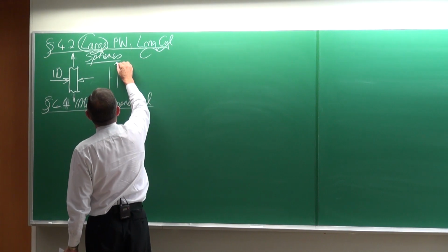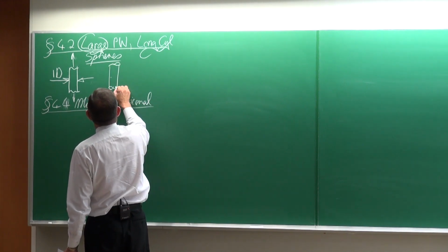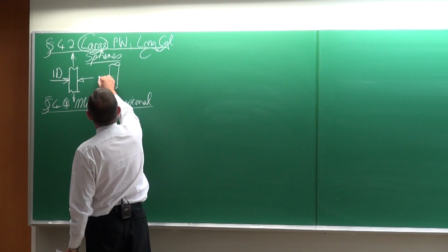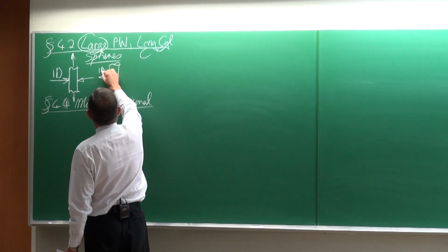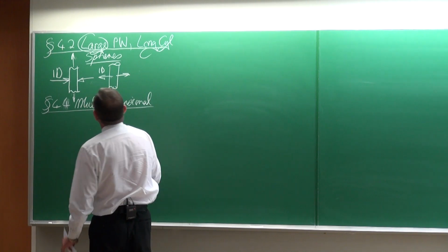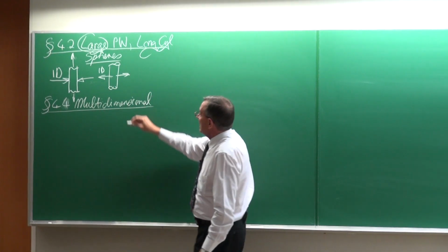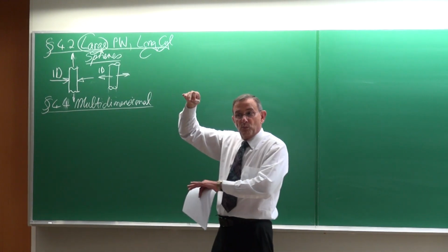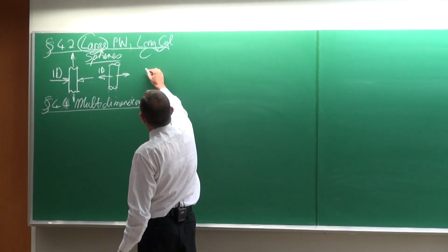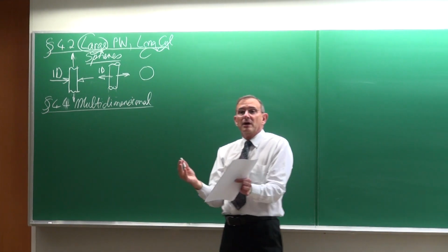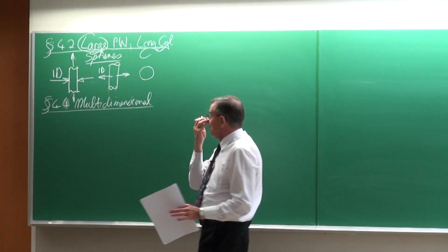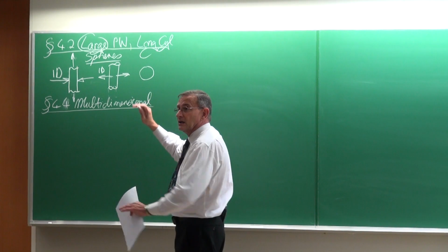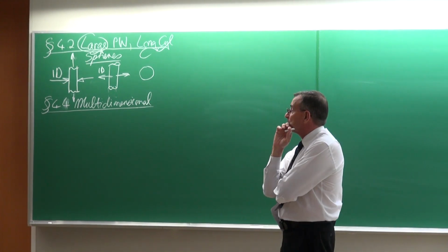And the same for the long cylinder. For the long cylinder, it was typically something like that. And again, the heat transfer flows out in only one dimension. And again, we ignore the heat transfer from the top and the bottom. The only exception, of course, is the sphere, which is one-dimensional, and we do not have to specifically refine that one.